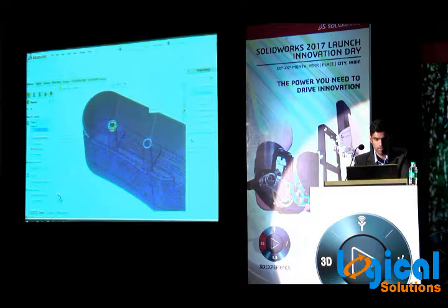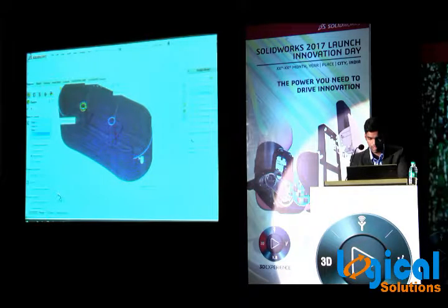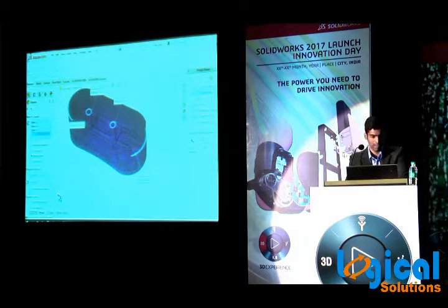Here the distance is 1 mm. You can directly double click here and give whatever distance. Like I am going to control this one with 0.5, and the other one, let's say, I am going to change to 0.3. So we have multiple options in this fillet and chamfer update.